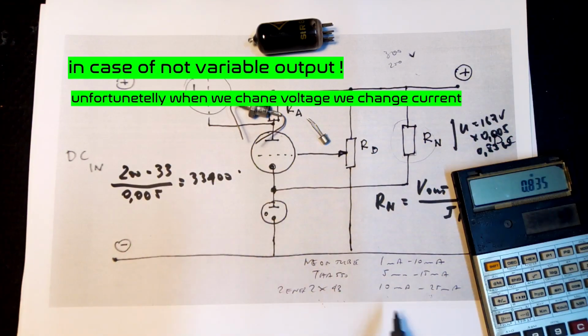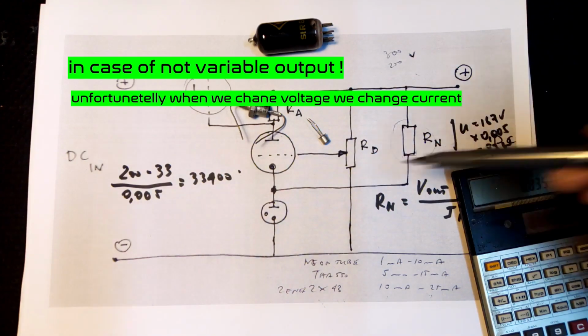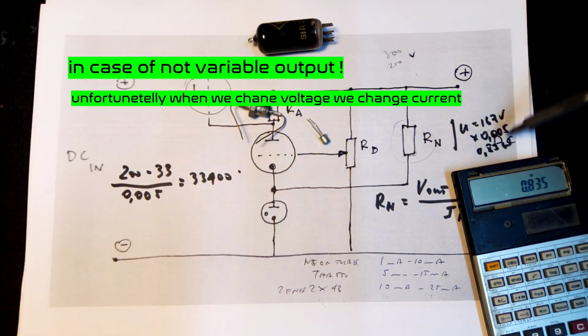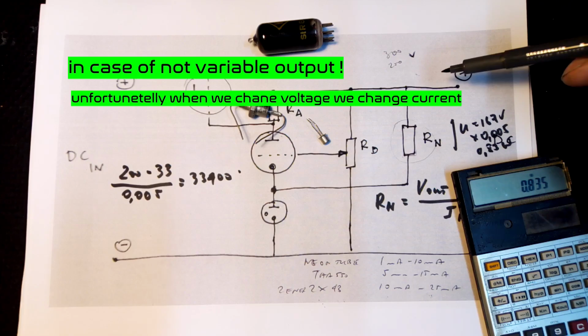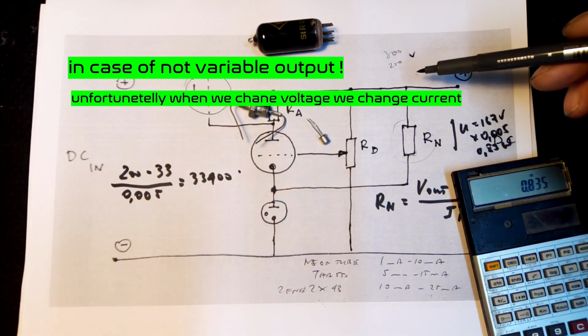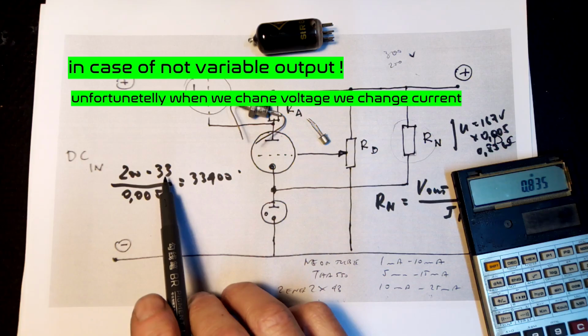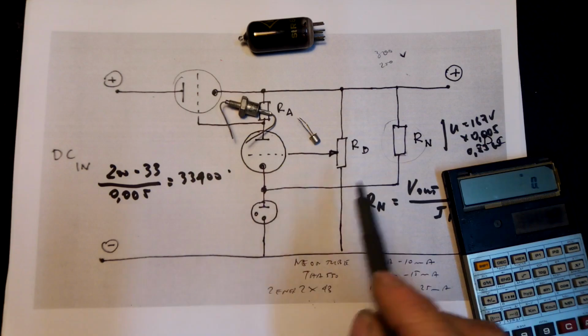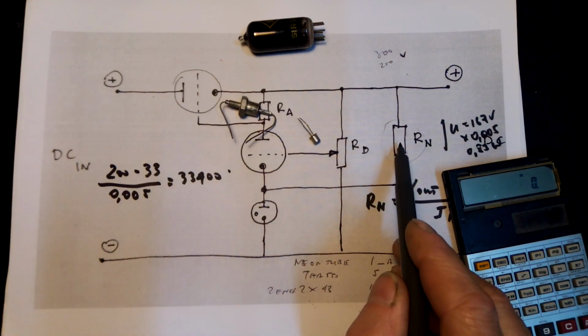So in case we choose the Zener diode even with this 43, probably we have to fit here 4-5 watt resistors. So you can calculate it. I don't want to make it longer, but this is what we have to do. And of course, when we go up, the current will rise. When we calculate at 300, it means the resistor will be same.